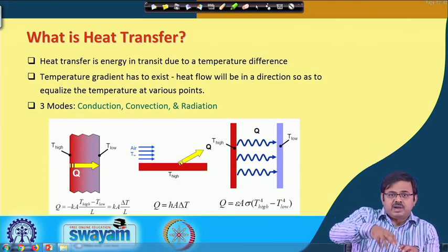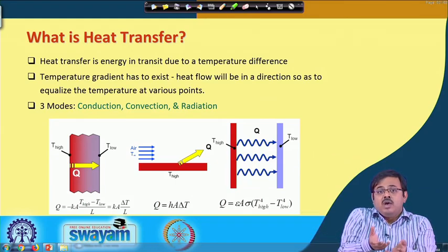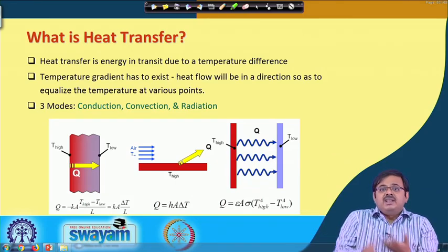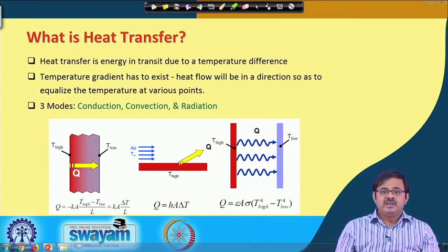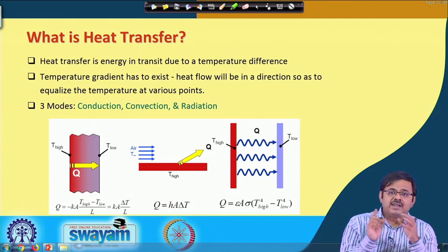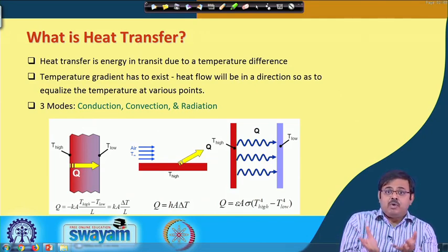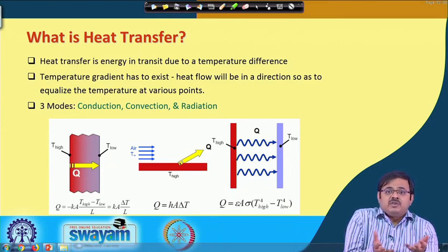As it moves up, there is a partial vacuum created, and cold air from the surrounding comes down to occupy that void, which in turn again gets heated and rises up. So, this is natural convection occurring due to density difference. The technical term is buoyancy induced flow, because of the buoyancy forces resulting from difference in density. All right. Of course, natural convection is a less efficient means, but it comes for free.